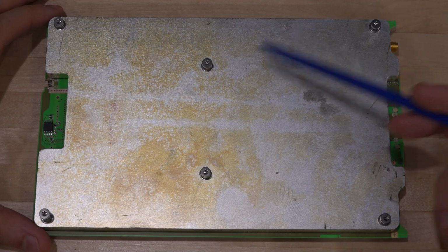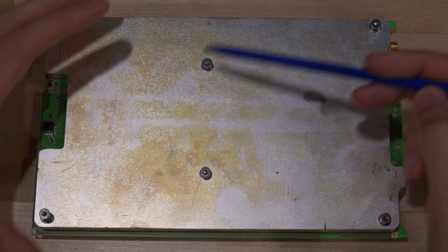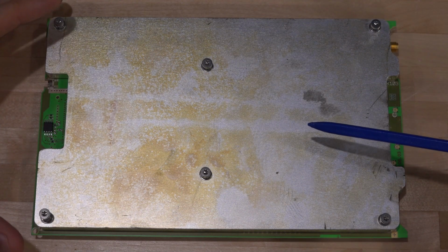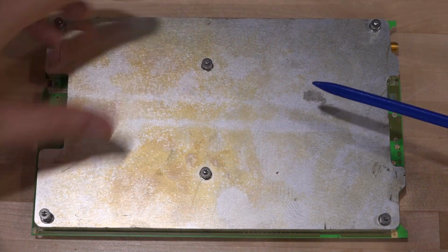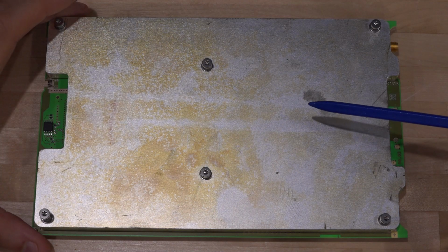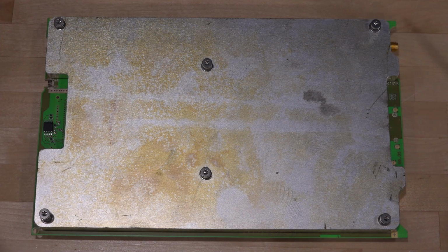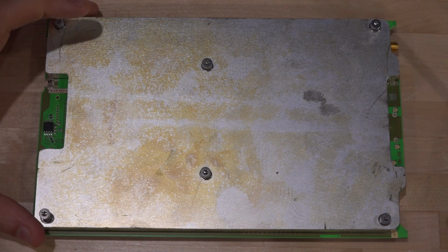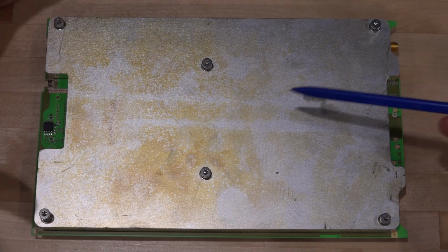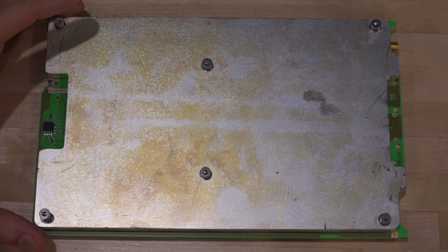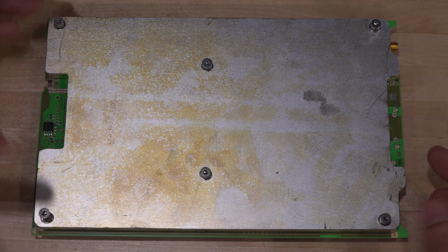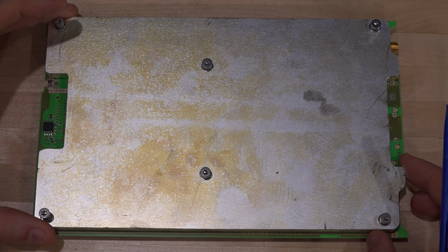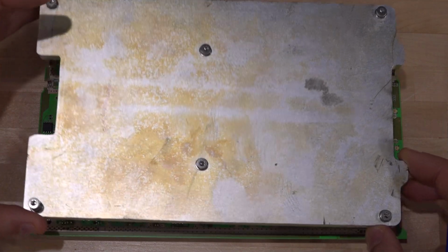I'm a little bit surprised at how few screws there are. Normally, you put a lot of screws on a board like this because you want to press down and really isolate the individual compartments underneath, which have to be isolated from each other. It may be that they just didn't need to do that. But if you've seen any of the other modules I've opened in the past, that's typically the case. If you want really good isolation, you have to press down on those conductive layers sandwiched between these things. So I'm going to remove this.